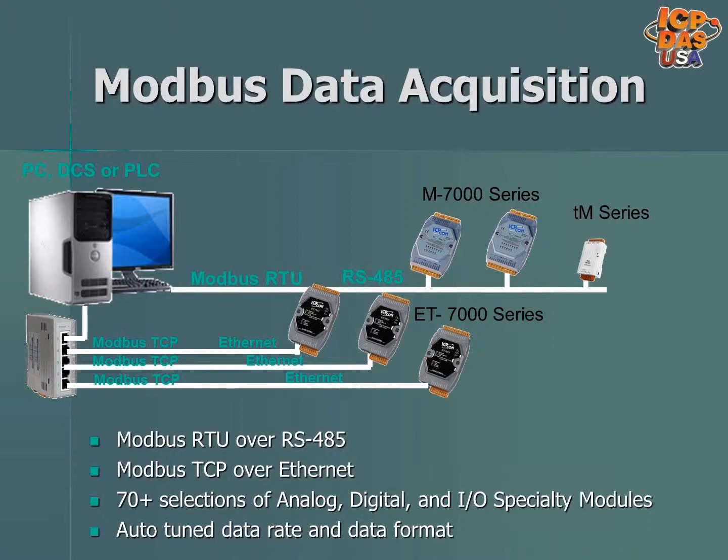Modbus TCP protocol is a variant of Modbus protocol. It was developed in 1999 to allow Internet and Ethernet access of Modbus devices. Modbus TCP-based equipment communicates over Ethernet cabling. Many buildings have Ethernet cabling installed, so adding Modbus TCP devices is convenient in many applications. Modbus TCP and Ethernet cabling supports communication distances up to 100 meters or 328 feet.